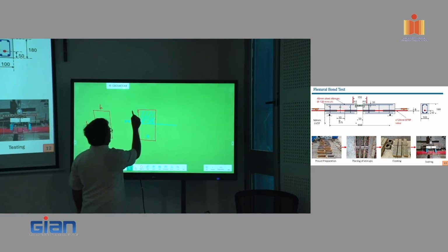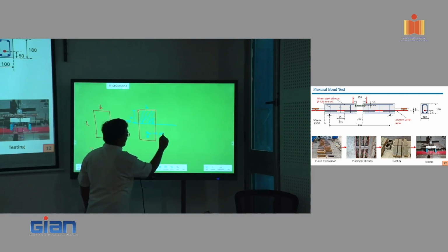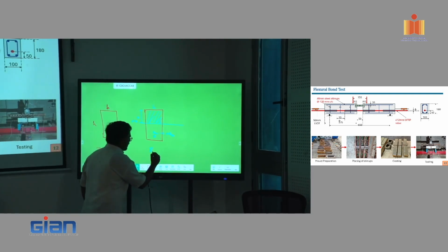So what I do is, okay, let's say this is X and this is B. So I take moment of, and then I convert this, let's say this is AST. This can be converted into modular ratio times AST for an equivalent area and then get my moment of inertia, let's say, which is I cracked.